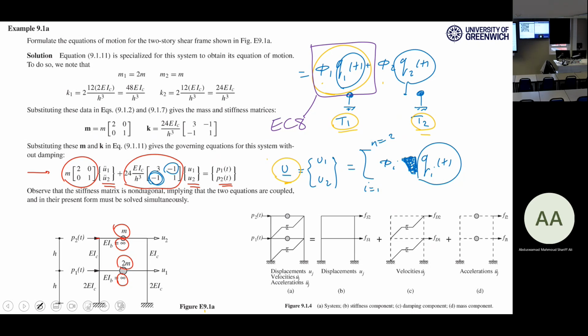And this means that the whole complex system can be simplified by a single degree of freedom system with a natural period of T1. For the single degree of freedom system, you have Excel sheets, you can calculate whatever you want, right? But with this assumption, this solution goes to Eurocode for seismic loading of the structures.